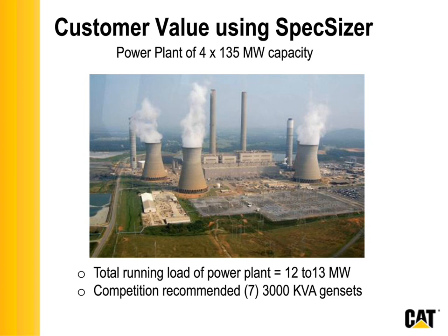Well, I looked at the sizing file. It was 19 load steps. And basically what it had to do with, in conversation with the customer, was something called duty point percent or load factor. In conversation with the customer, I learned that the duty point or the load factor of all 19 loads was not 100%. It was just 75%. So we're going to talk about that application right now. We're going to get into that.